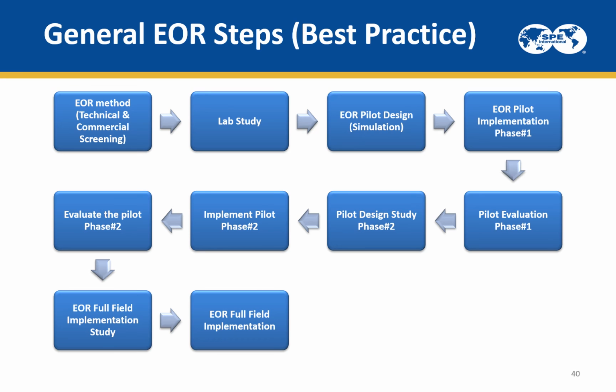Again, I need to remind about the general steps for the best practice for EOR. This is 10 steps. It should be followed as a standard, starting from technical and commercial screening, then laboratory study, then pilot designing, and for phase 1, implementation for phase 1, evaluation for phase 1, and then we will come up for pilot designing for phase 2, implementation of phase 2, and then evaluation for phase 2, and finally we will go for full field study and then implementation for full phase.